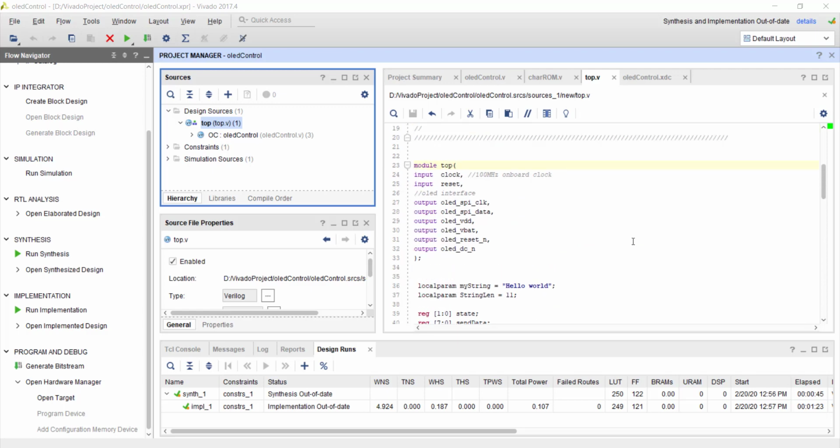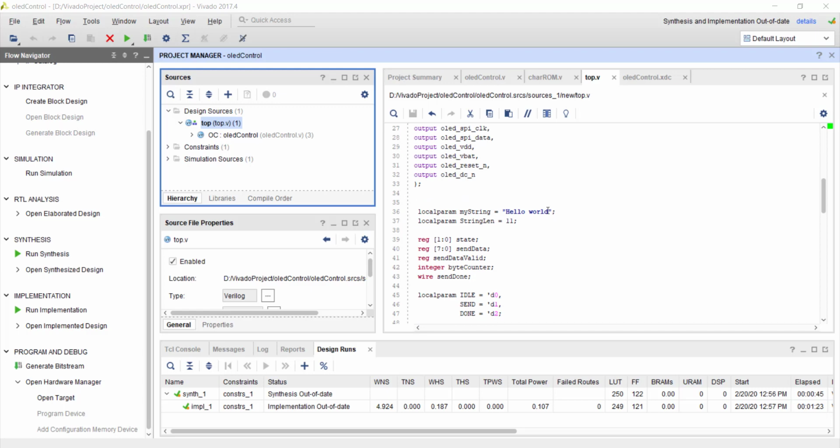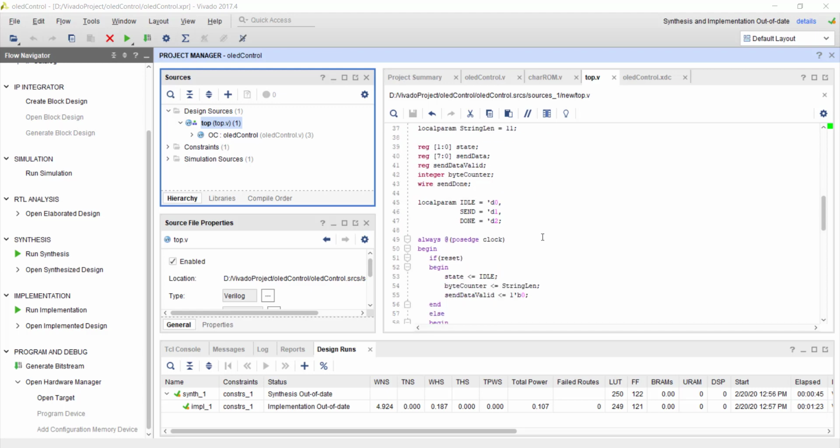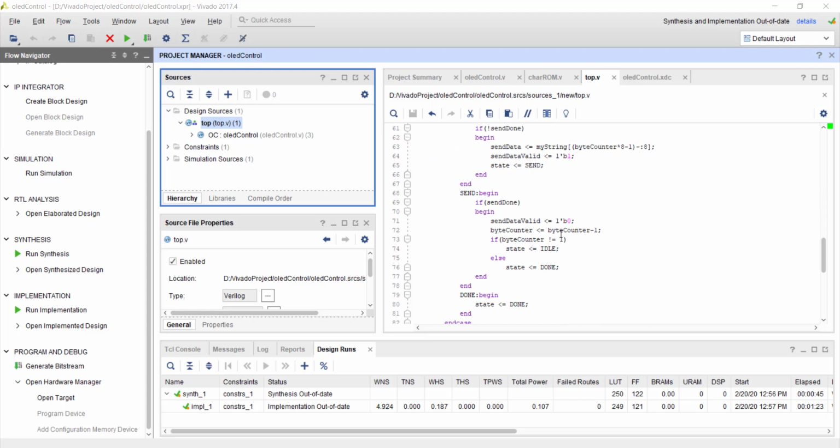So what is this top module doing? For example, providing the string and the valid signal, and checking for the ready signal, basically the state machine. This part we will be modifying, and instead of using a state machine here, we'll be using some registers. The initial step is exactly the same as for developing the GPIO IP. We will start with the IP generation wizard of Vivado, specify how many registers there should be, and then interface those registers with my current logic.